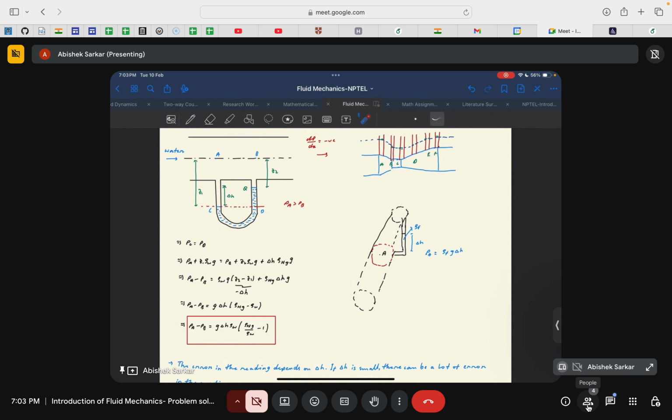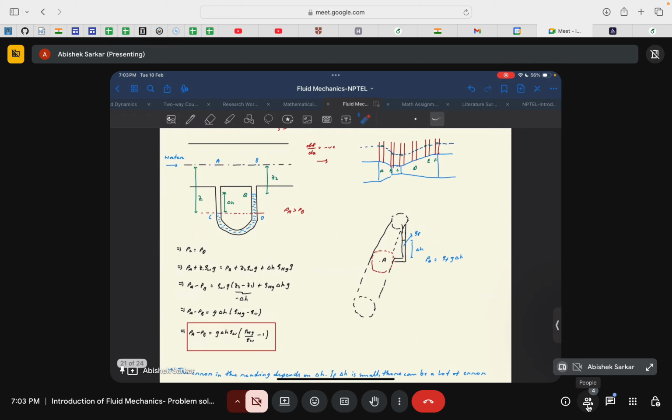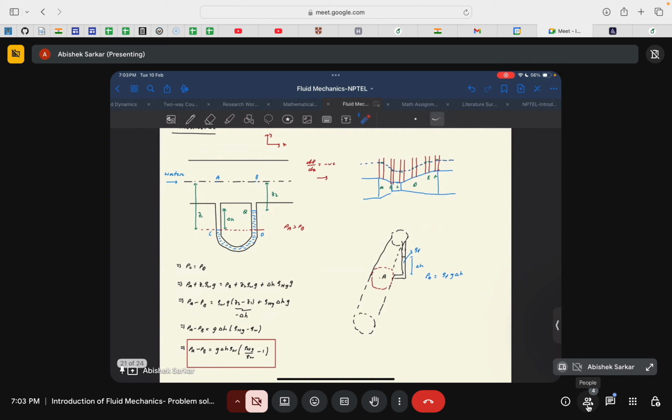So with that, let us take this simple example. There is a flow of water from point A to B. For flow to occur from point A to B, the pressure at point B has to be lower than the pressure at point A. Then only can the flow occur in this particular geometry. In the case of a duct or pipe, for a favorable flow, there has to be a negative pressure gradient. So we will have the pressure at point B lower than the pressure at point A. Then only could the flow occur in this direction.